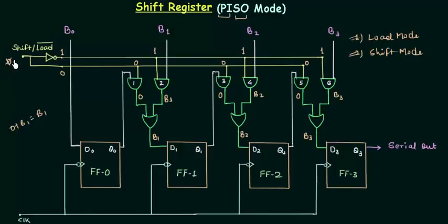To 1, and because of this we will have a 0 here, 1 at this point, and you have to switch the inputs to your AND gate also. So we have 1 as the first input to gate number 1. In the same way, we have 1 for the gate number 3 and 5, and 0 for the gate number 2, 4 and 6. Because of this, we have some changes.